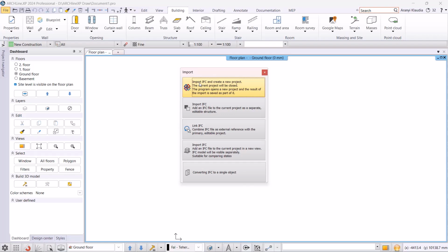IFC provides 3D geometry and data exchange between different CAD BIM design software. The most valuable property of the IFC format is preserving architectural elements and properties. The properties of elements, like walls and ceilings, remain unchanged, though some compromises may occur due to the current technology levels. IFC-based data exchange has a much larger capacity than the more widely used DXF DWG-based data format.